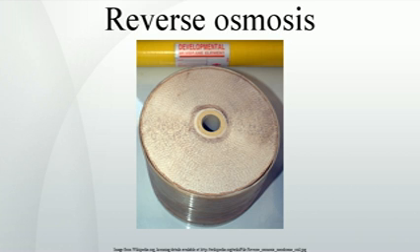Desalination. Areas that have either no or limited surface water or groundwater may choose to desalinate. Reverse osmosis is an increasingly common method of desalination, because of its relatively low energy consumption. In recent years, energy consumption has dropped to around 3 kWh per meter cubed, with the development of more efficient energy recovery devices and improved membrane materials. According to the International Desalination Association, for 2011, reverse osmosis was used in 66% of installed desalination capacity, 44.5 of 67.4 million meters cubed per day, and nearly all new plants.